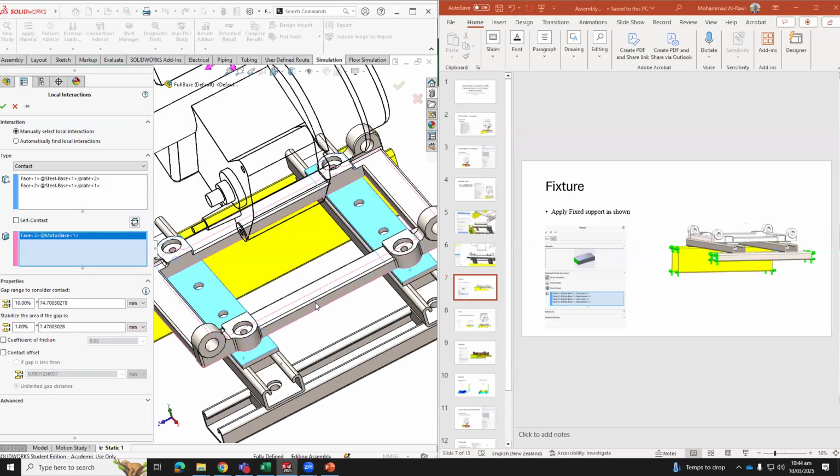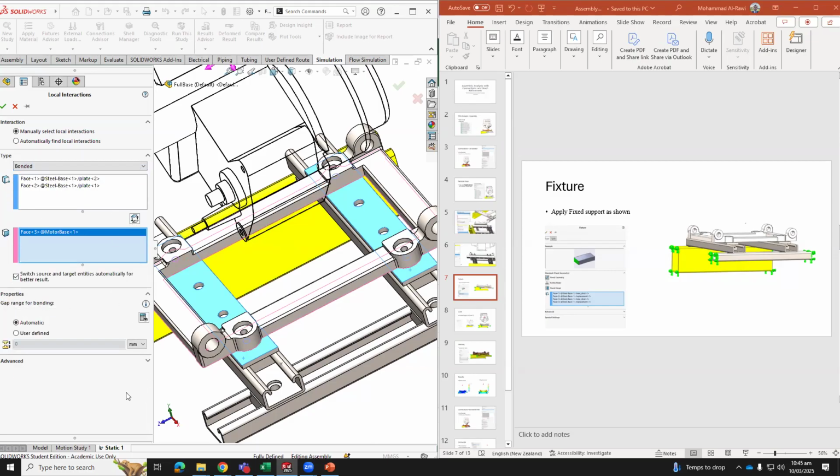Third one. So you select that face, yes, that face. And then here, you turn it back, turn it on, down. So it's kind of like whatever is attached to each other. Is this bonded or contact? Bonded, all of them bonded, we're choosing here. So the type of contact is bonded, the first one. So bonded, and then you get that face between them.